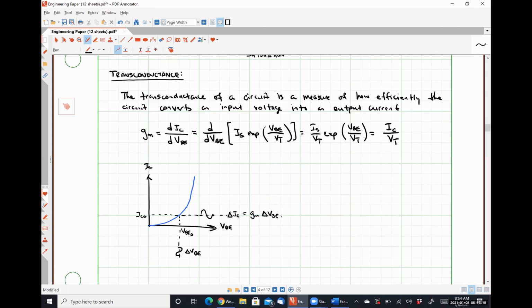It doesn't really come into play a whole heck of a lot until you run into situations where your ripple signal winds up changing the operational mode of the amplifier, which is possible, right? So if you have a significant change in VBE that would cause your amplifier to leave the forward active region, you'll start to see lots of distortion, which is something we'll talk about later.